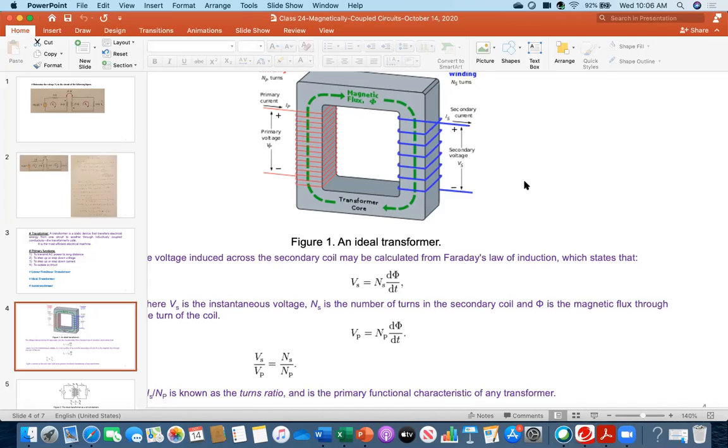Because the transformer got overloaded, during summer most of the people start using their air conditioning system. But typically it happens around noon or early afternoon. It is overloaded and then the transformer got disconnected. So if the transformer is disconnected, then the connected loads will be in the dark. They will not get the power.